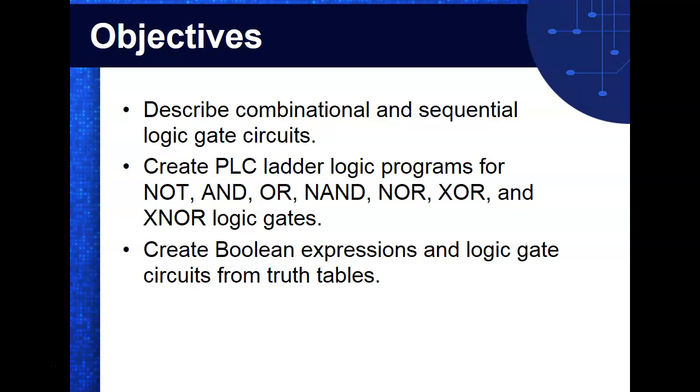And so a scale has an auto zero on it, and what it does, the scale's got a motion detector on it. And what happens is you auto zero it every once in a while until you see motion, and then you stop. And they bought it without that. So I was assigned the task of designing an auto zero circuit. So I came up here. I thought I had to monitor all the digits. There was like 6 of them, and it was a BCD, so that would be 6 times 4. So I was monitoring 32 inputs to fix the motion.